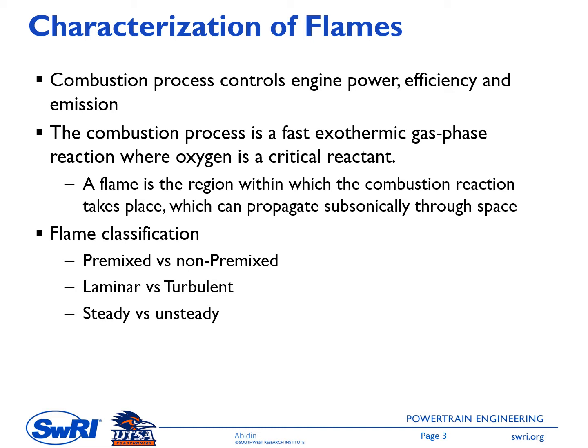In the spark ignition engine, the combustion process is initiated by a spark generated between the spark plug caps, and then a flame kernel is created by this spark discharge and propagates across the cylinder to the combustion chamber walls. At the walls, these flames will be quenched or extinguished as heat transfer and destruction of active species at the walls become the dominant process.